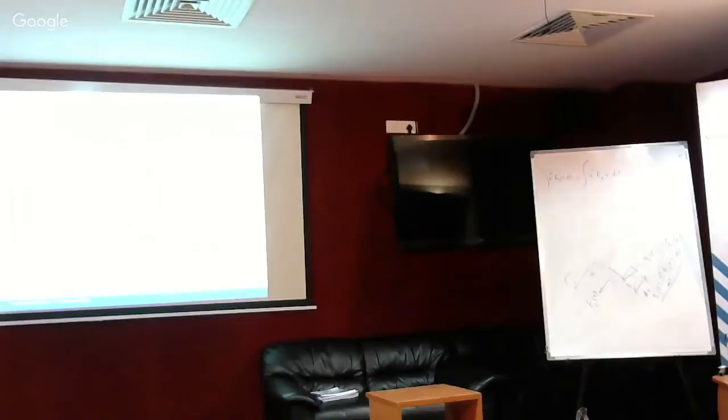And these are some time history responses. The black one is under control. These are controlled with various weightings. These weightings correspond to various forces that we apply for the actuator. And this is a spectrum of the response showing that there was a control one, there's a peak over here, and you can see that 0.2 hertz is the rotational frequency.